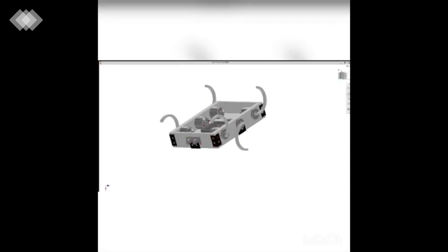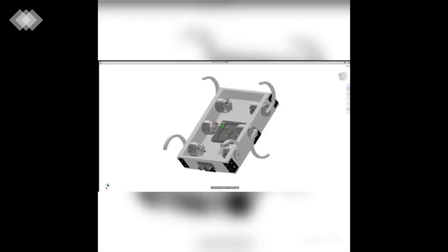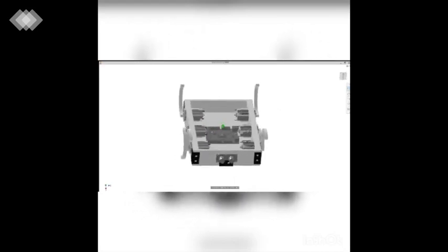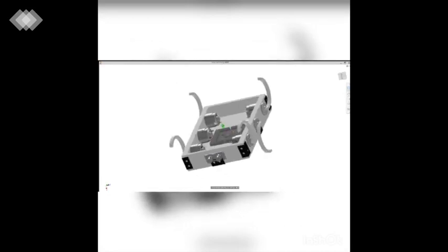Six C-shaped legs, which are used for the locomotion, are attached to the shaft of the DC motors. There will be a difference of 8 cm between shafts of two DC motors because the movement of one C-shaped arm should not interrupt the movement of the other. C-shaped legs can move in forward as well as backward direction based on the clockwise and anti-clockwise rotation of the DC motors. This is how the movement of the module takes place. With the help of the ultrasonic sensor, if an obstacle is detected within 20 cm, the model has to stop its movement and an LED light glows indicating the presence of obstacle.